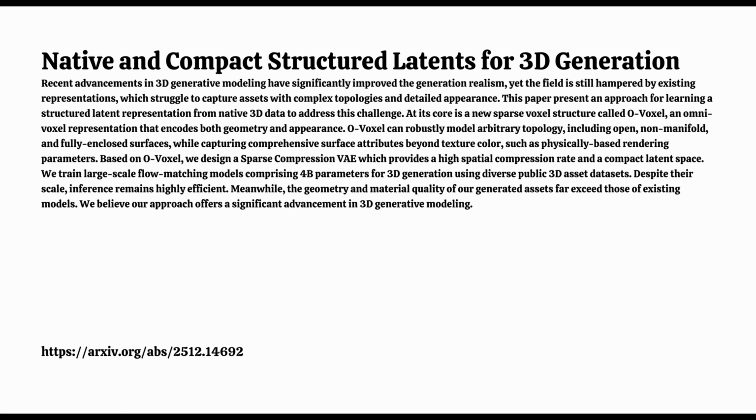It's also worth noting the flexibility built into that material generation stage. Yeah. It is. Because the material generation stage is decoupled, it can be used independently for 3D PBR texture synthesis. And this is a major technical advantage. Because it operates natively in 3D space, it completely avoids the inconsistencies and seam artifacts that are chronic challenges in, say, multi-view or UV-based texture approaches, where you're trying to stitch flat images onto a complex 3D shape.